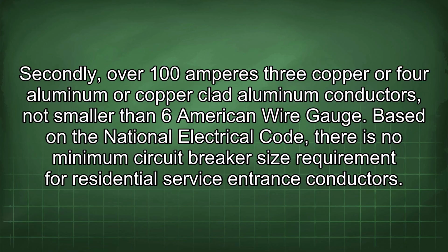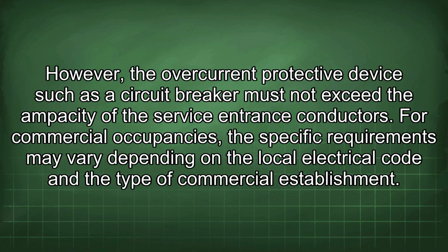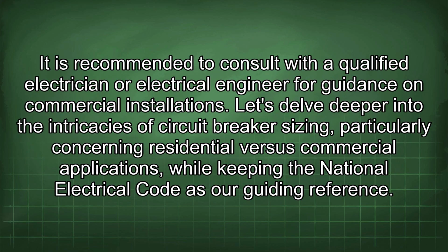Based on the National Electrical Code, there is no minimum circuit breaker size requirement for residential service entrance conductors. However, the overcurrent protective device such as the circuit breaker must not exceed the ampacity of the service entrance conductors. For commercial occupancies, the specific requirements may vary depending on the local electrical code and the type of commercial establishment. It is recommended to consult with a qualified electrician or electrical engineer for guidance on commercial installations.